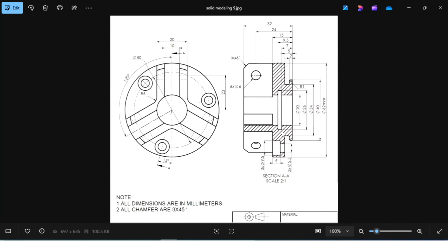This one, the step cut, is 26 mm diameter. Outer step, this is 34 mm. The outer diameter of this one is 40 mm. The main diameter or the outer diameter of the biggest circle is 62 mm.